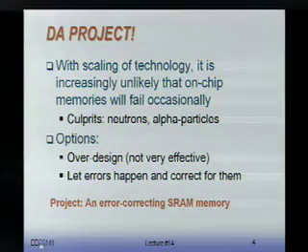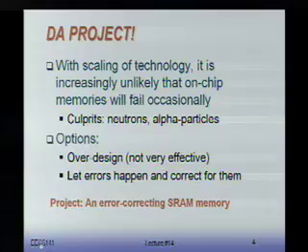The problems are harder with errors that occur occasionally, things that we call soft errors. They're not hard. It's not because it fails that it's going to fail forever. It fails one time and then might work again. One of the main culprits of those things is what's called an alpha particle, and other things are basically neutrons. Actually, it was around the late 1970s that people designed the first DRAMs, and they saw that something occasionally was going wrong. An error was happening in memories. They did simulation after simulation and couldn't figure out where it was coming from.